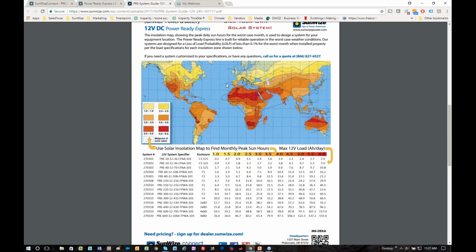question, I'm going to go to the sun hour columns first. And in our case, we did a sun hour value of 3.7. So we're always going to use the next lowest value because that is the limit. So we're going to go to the 3.5 sun hour column, and we're going to come down until we see our load in question of 25.